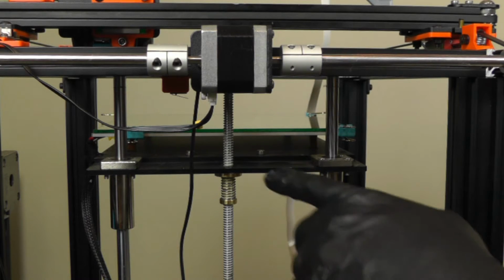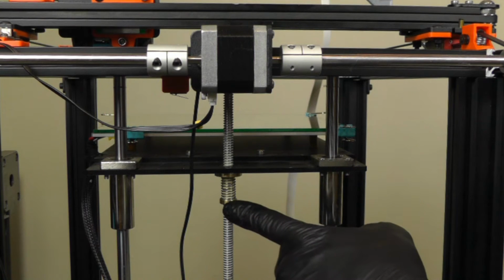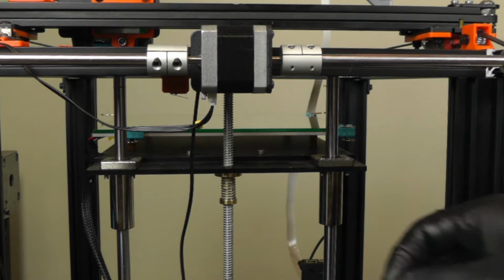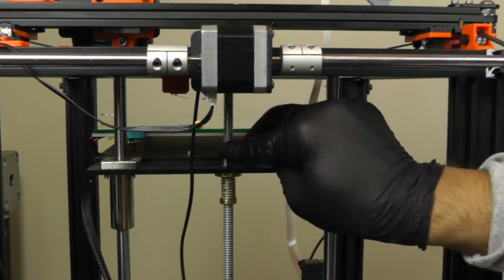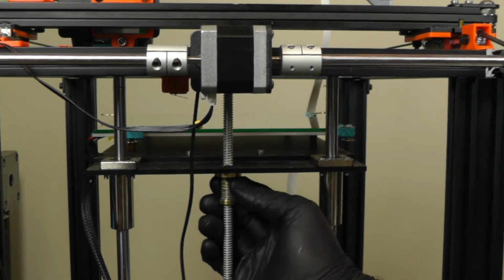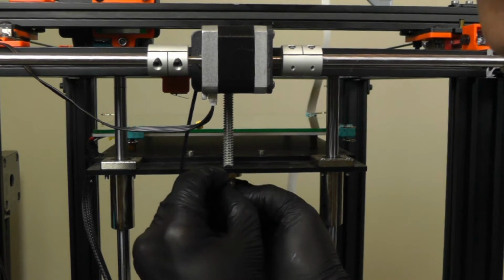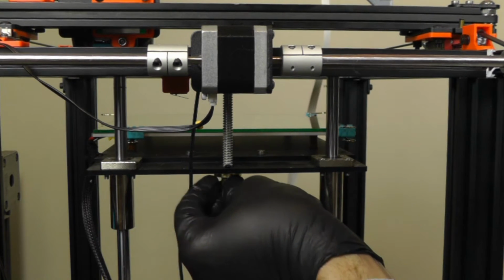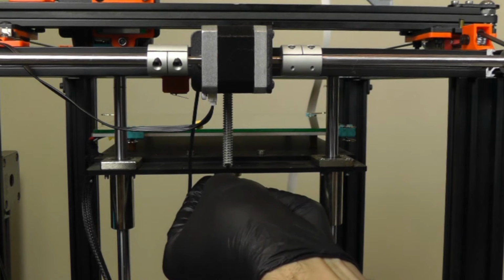So at this point, the screws that came out of here will not go into this nut because these holes are not threaded. So what we need to do is create our own connection using an M3x12 screw and a washer and a nut, a lock washer particularly, if we have them. We're going to pull down on that spring before we put it on here so that the spring doesn't get in our way.